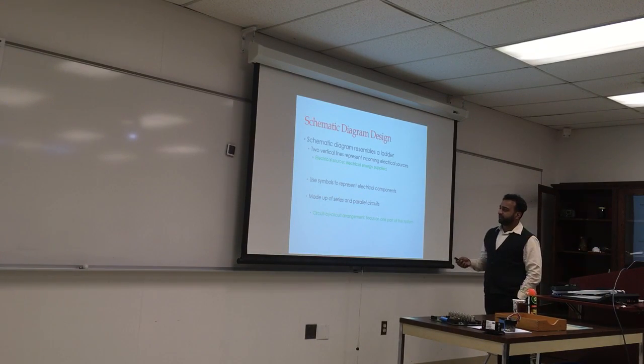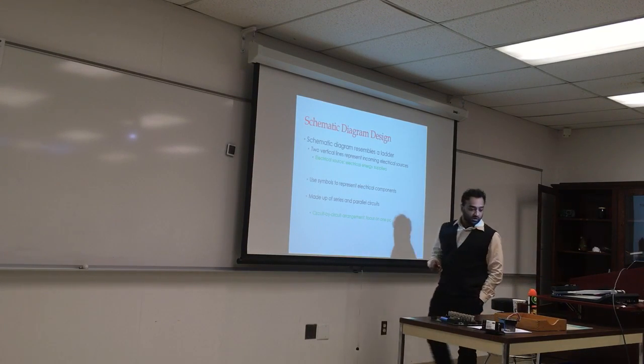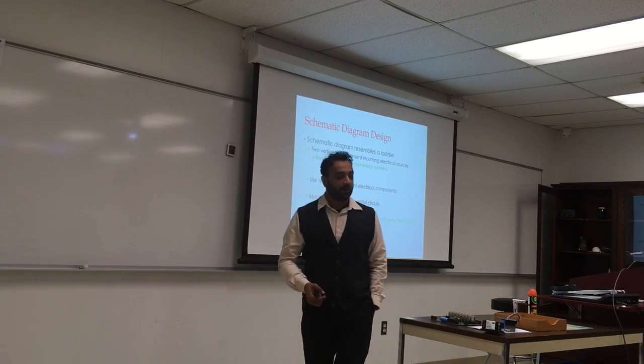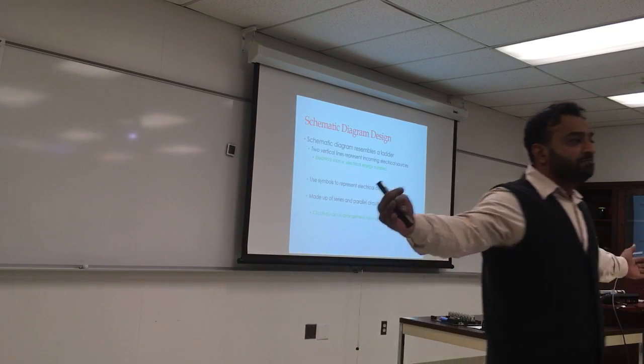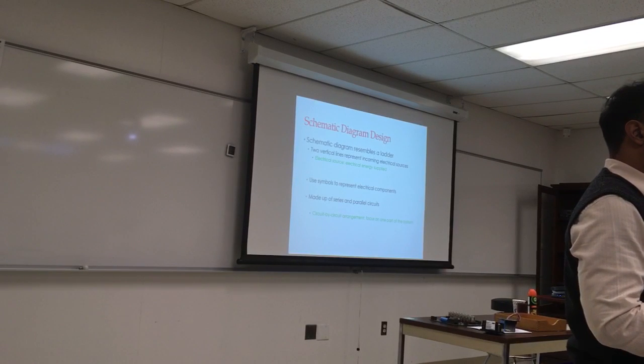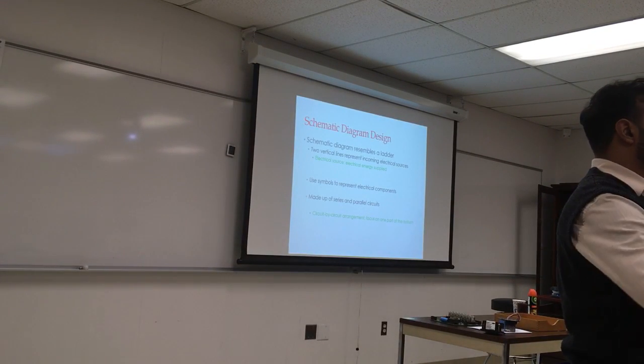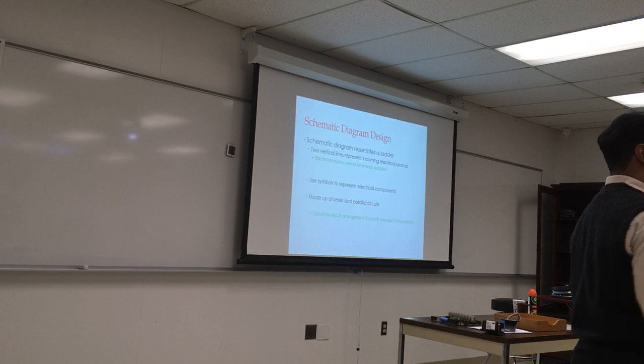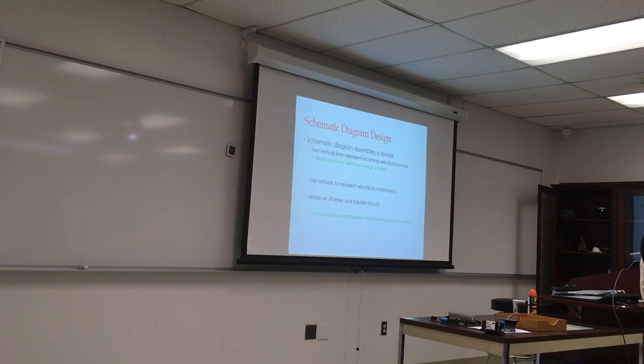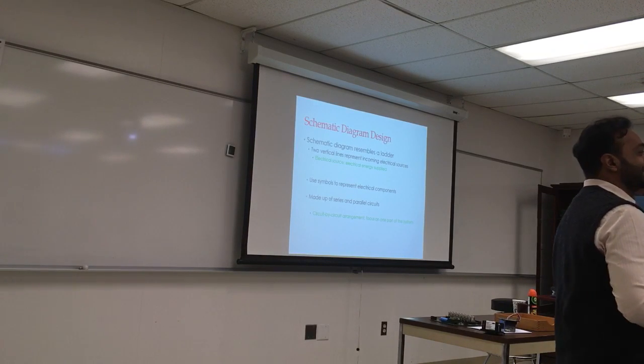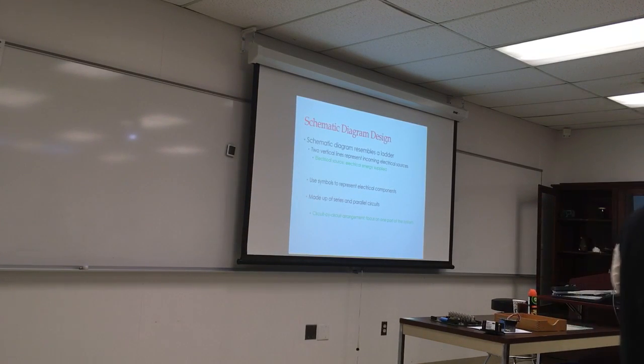Components are made up of series and parallel circuits, arranged circuit by circuit, so focus on one part of the system. I will show you some overwhelming schematics where you have big diagrams and they just put every component spread out by itself. So focus on your circuit, try to trace it out. And again, the first thing you do when you look at a schematic is what? Do not panic. Just look at it piece by piece and it should make sense.